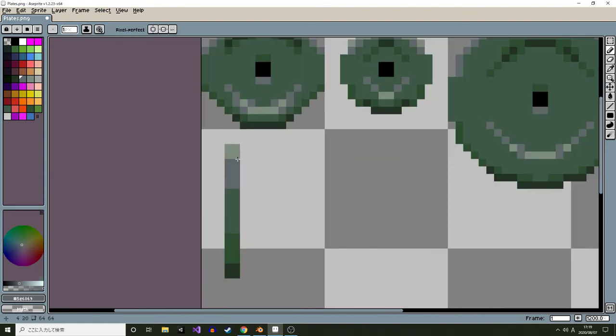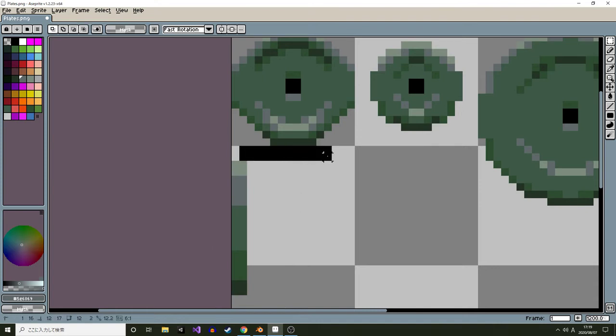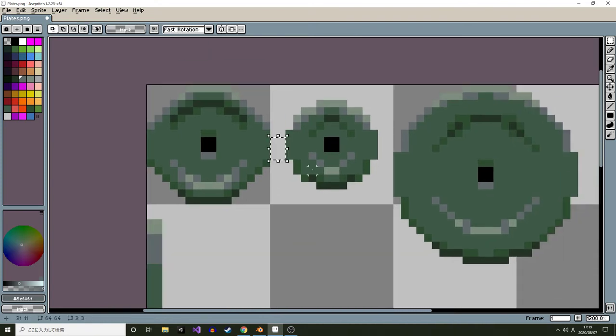Should we do anything to it? Nah, let's leave it like that. That's fine. Okay, so we're going to leave 2 pixels, sorry, 2 pixels for texture bleed later. Always leave at least two pixels.